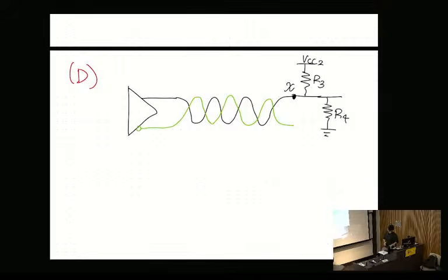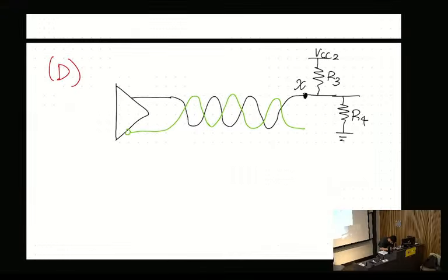Whereas at really high frequencies the wavelength becomes really short, so now we have to consider it not just as a signal, but as a wave that propagates through different mediums. It's like trying to push a wave from water to oil. Some of it is going to transmit through, a lot of it is going to reflect back. So the impedance across this line is 50 ohms, and we need to make sure that this impedance RL that's seen by the transmission line is also 50 ohms.